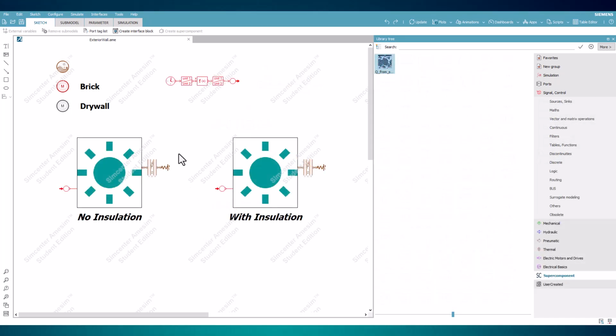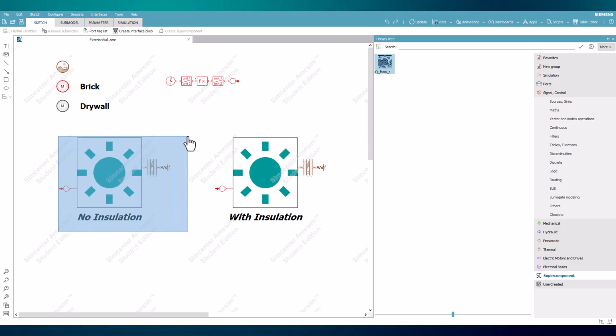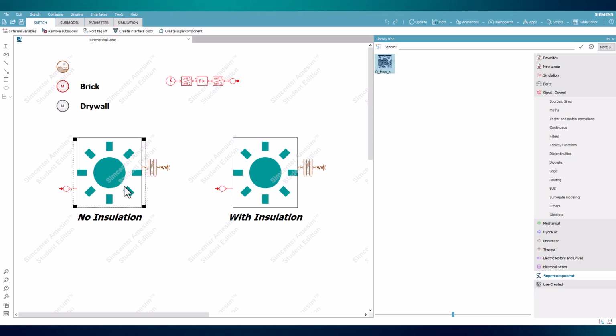Walking through the changes completed, the signal logic for the temperature of the surroundings depending on the time of day has been set to be sent to both models with the form of dynamic transmitters and receivers. The dynamic transmitter attached to the output of the temperature logic above will send the same value to each of the receivers set to it, which are both set to input a signal to the newly added supercomponents.